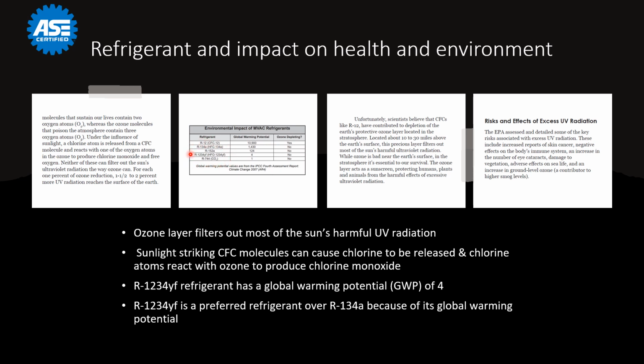So what you're going to see is a lot of different components with the R1234YF. And what I mean by different components is that their design is going to be different. The condensers are going to have thinner passageways than R134A,